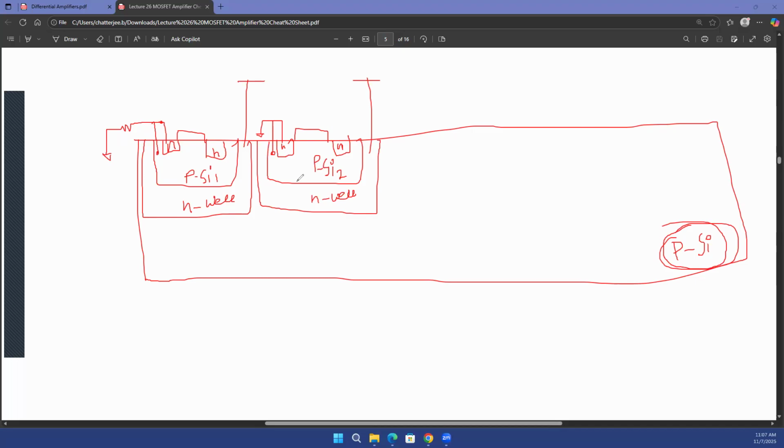Right? In the original wafer that you buy from the market. So that's a logistical limitation. If you buy a wafer from the market, it will just be that p silicon. You'll not get those isolations. So you can create shallow trench isolations, STI. You might have heard about some of those terms. Or you can create these isolations. You can ask the foundry to create these isolations for you, which means you have to pay the foundry more. So if you're ready to pay more, this can be done. Questions?